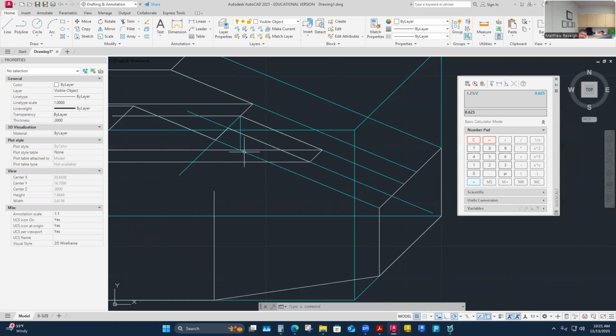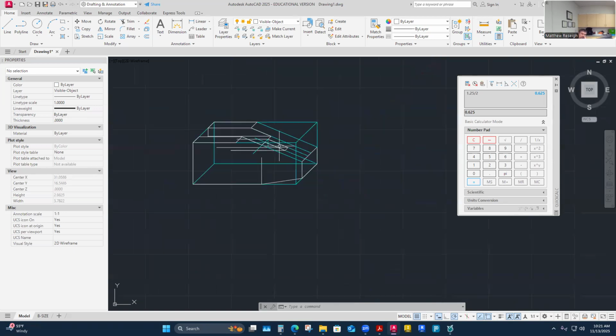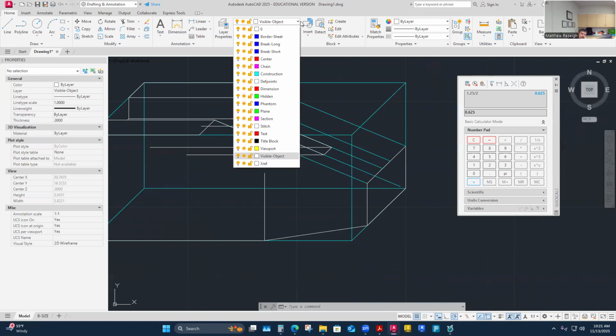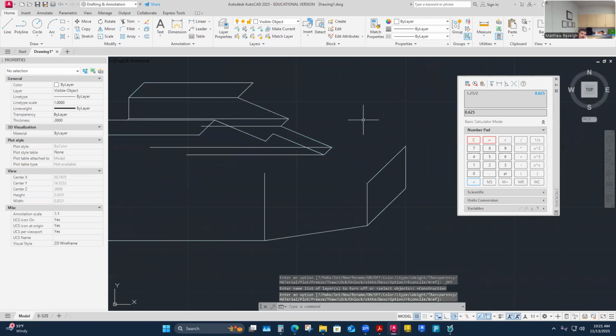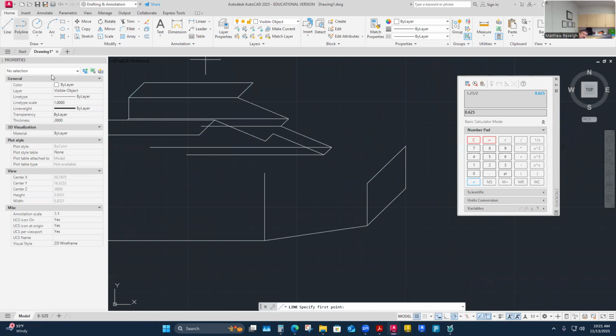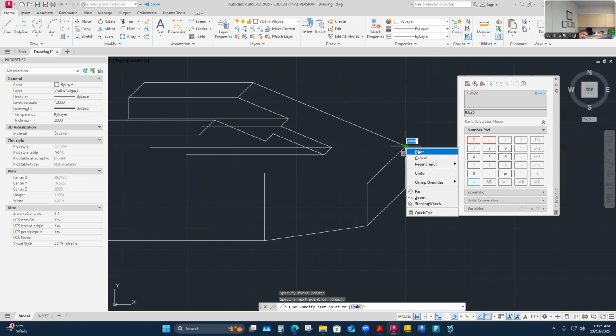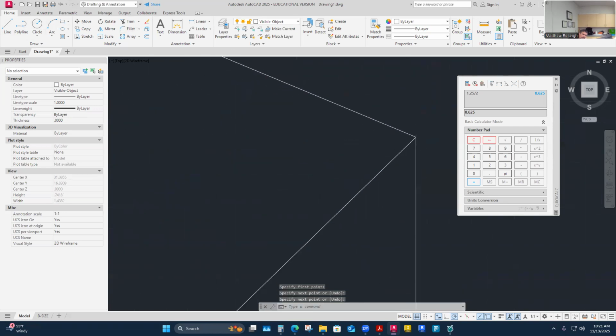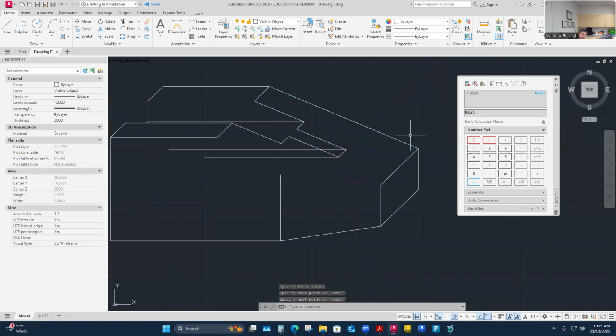What I've got is a bunch of visible line work that I need to trim out now. And maybe I can turn off my grid and just take a good look at this. When in doubt, turn this off and see what's missing. This one I made into a construction line is why, and that's what I would just copy. And so I'll redraw it. And then all of this is going to get trimmed.